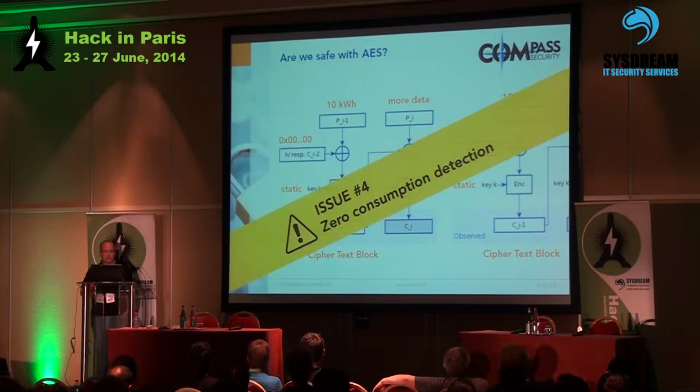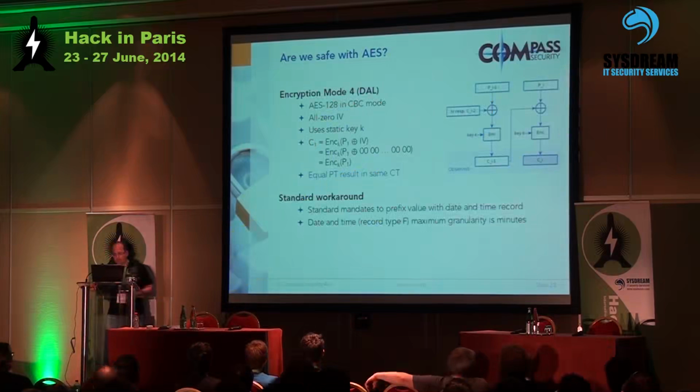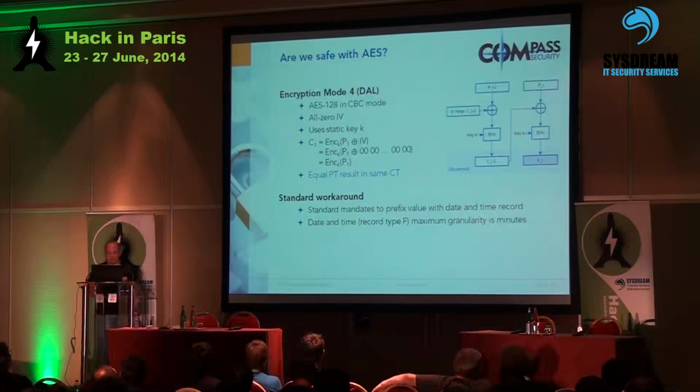But they were pretty clever. They mandated to prefix the value with the date and time record. And if you flip through the standard, you will come across the date and time record. Unfortunately, the date and time record is just minutes. And if your meter is going to send you information every 10 seconds, you're lost. So it doesn't help. There are more actually, but you must figure it out yourself.